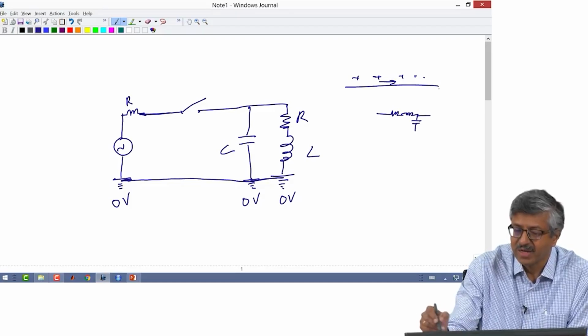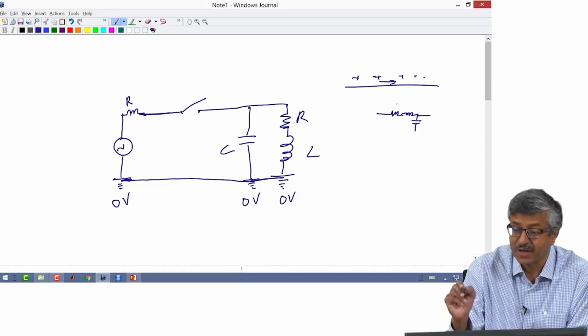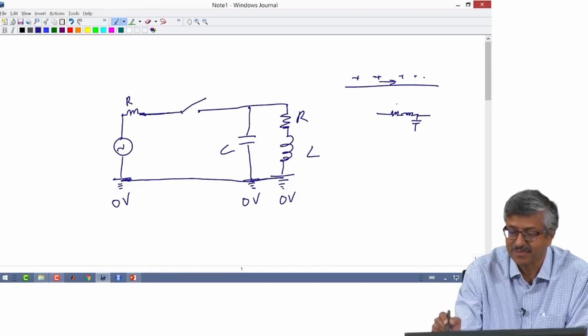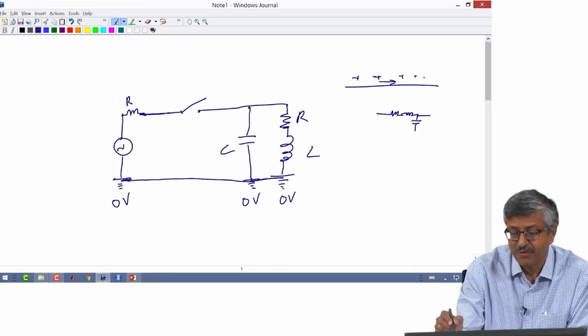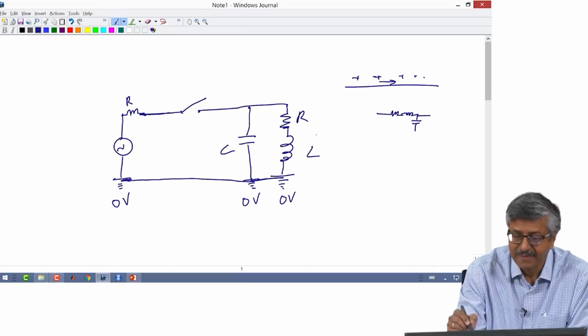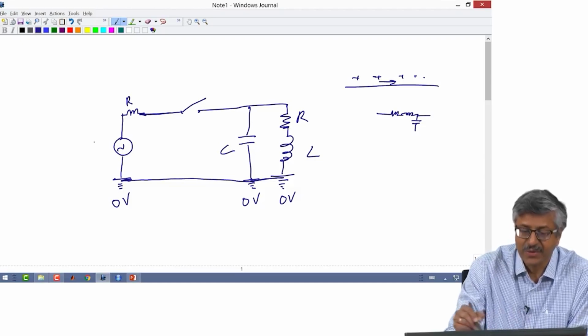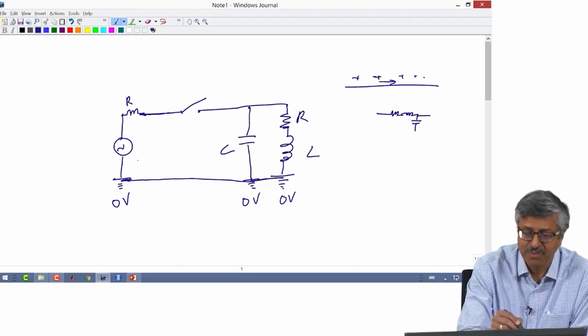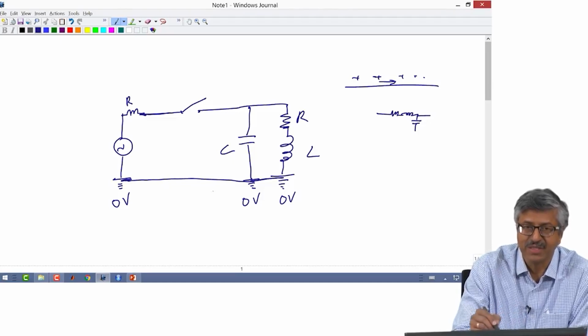So what we call a plain conductor of 0 impedance is actually an impedance network under high frequencies, when frequency is increasing, not for DC. Even for DC you can have some resistance, of course. Then the capacitors also are not ideal. So your real circuit under high frequency is much more complex than what we see over here.